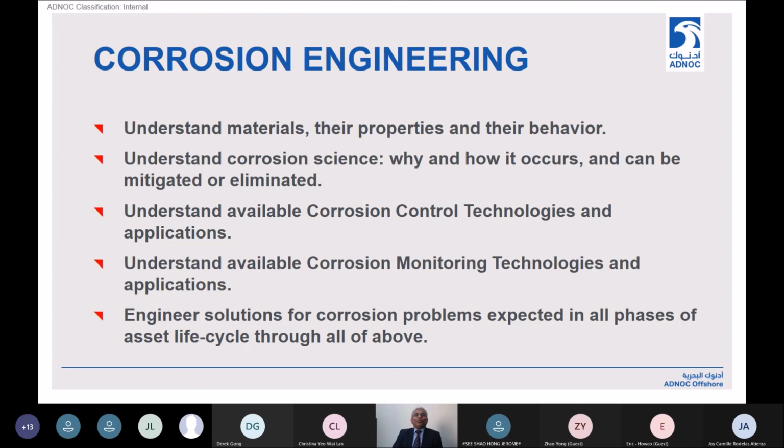Engineering solutions for corrosion problems, that's a very important aspect. Corrosion problems, for example, in the upstream business that I serve: it's only a prediction as to what's coming out of the reservoir. Based on this prediction, we design the facilities, including selection of materials and corrosion control philosophy. We implement them. In the early phase of an asset's life, you need to check what's changing from the original predicted or estimated parameters of the fluids coming from the reservoir, and you need to take early action, solving problems possibly before they become beyond our control.